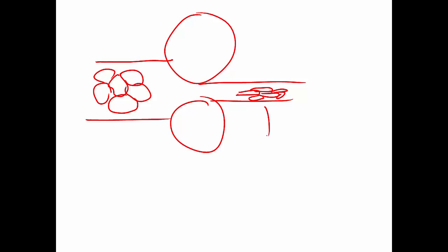And so that is what we call the morphological texture. And the next thing has to do with the orientation. The substantial plastic deformation of this process is going to create preferential orientations for the grains in the systems, because plastic deformation implies that the crystal lattice essentially rotates, and this rotation produces systematic orientations. They are no longer randomly oriented.